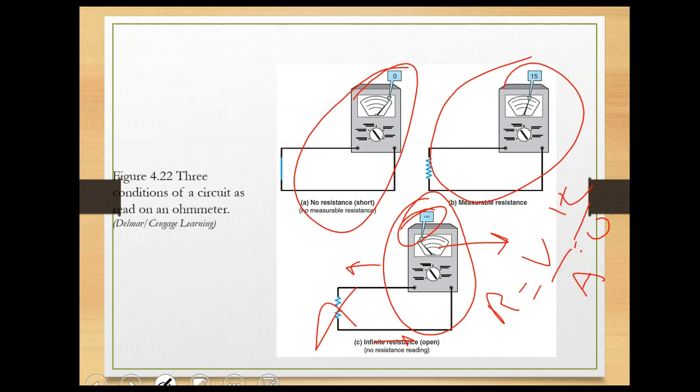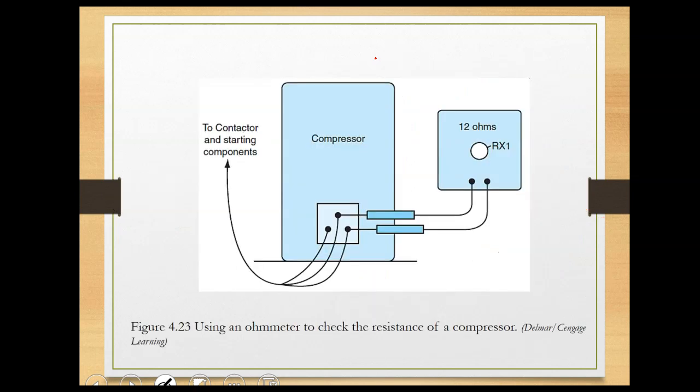But that's again in analog, and we don't use that anymore. Usually now you'll get a 0 if you have a short, and if you do continuity, even if you get 0, you will not get any beeping sound if you have an open circuit. I hope this illustration makes it a little bit clear.